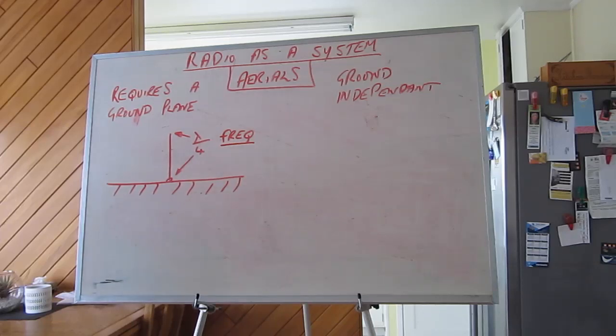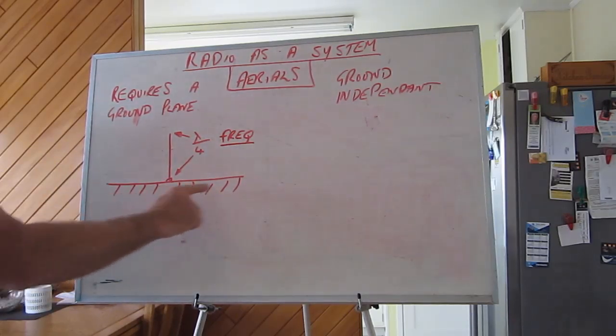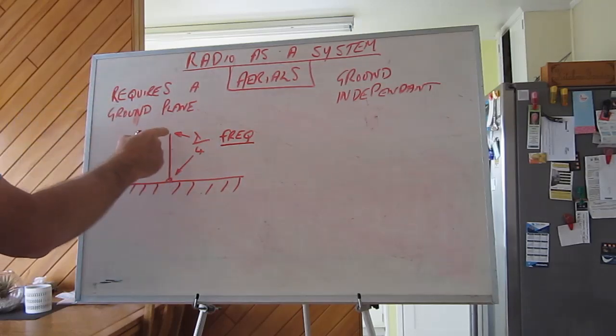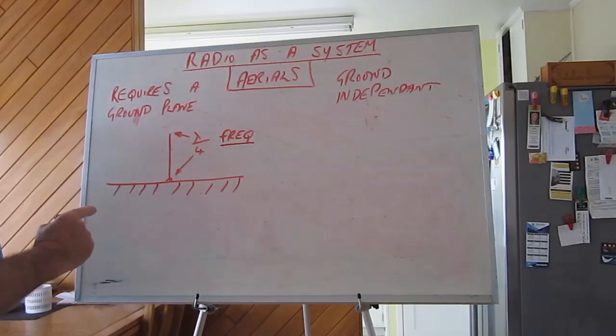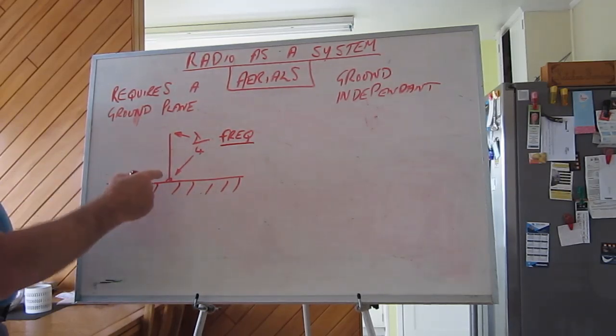Now that's very fundamental. The crazy thing is, I find a lot of antennas that have just simply been taken out of the store and bolted on. Obviously it's not been tuned to a quarter wave. It gets worse if it's not fitted even on a ground plane. And that's a fairly fundamental thing we need to do. We need to make sure that we're trimming the height of this antenna as a quarter wave dependent on frequency. And there are plenty of published charts to give you this height either in inches or millimeters.